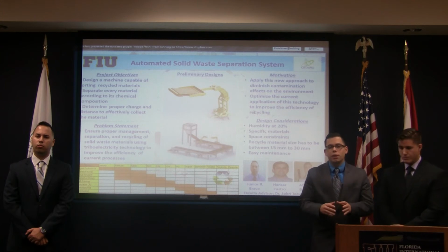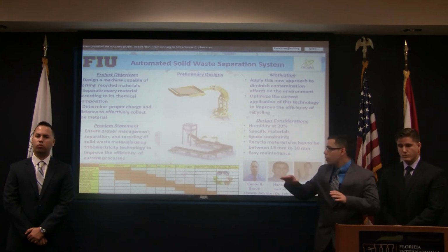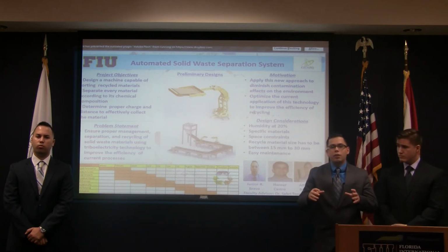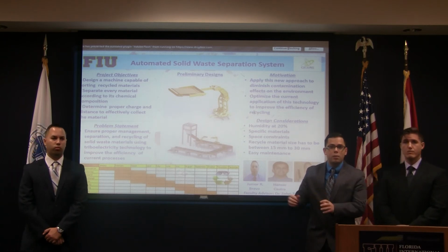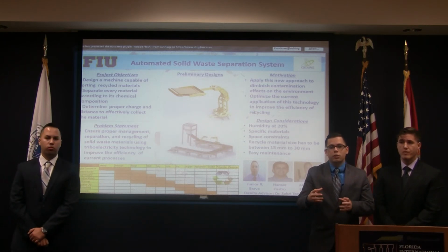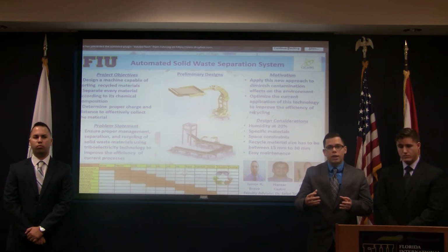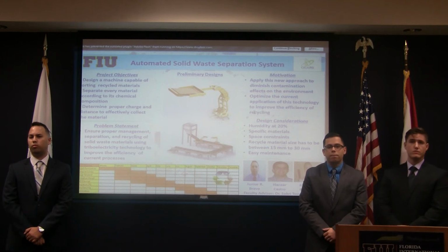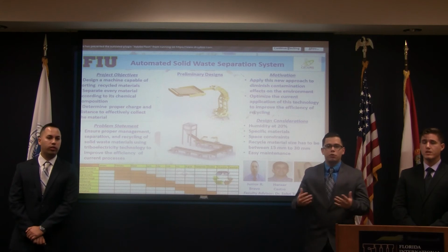All this process has to be done with a relative humidity in the environment of around 20%. To do that, we have to enclose the whole system and use a dehumidifier to reduce the humidity that already exists in the environment. At that humidity we will have a very good attraction to create static electricity. I asked because when I see the conveyor itself, it seems open, right? Yeah, it seems open, but for simplicity,